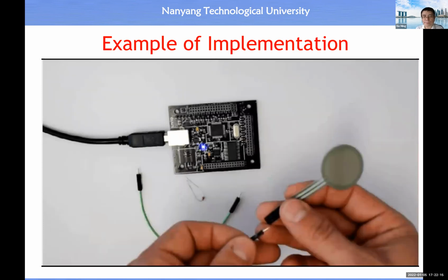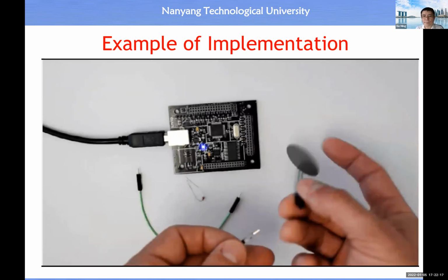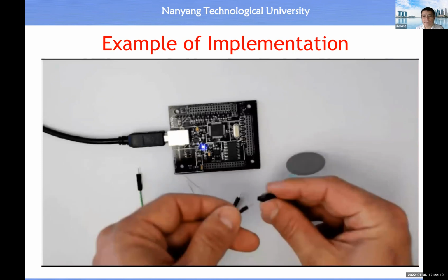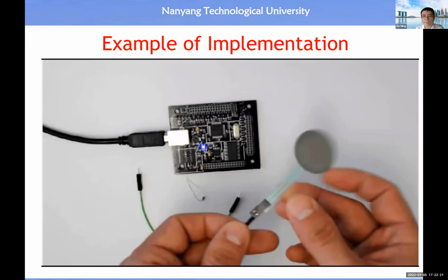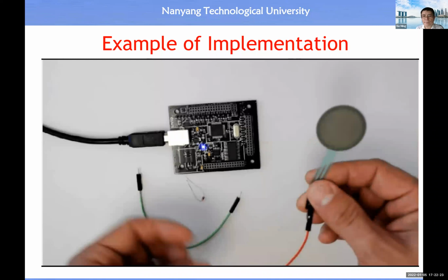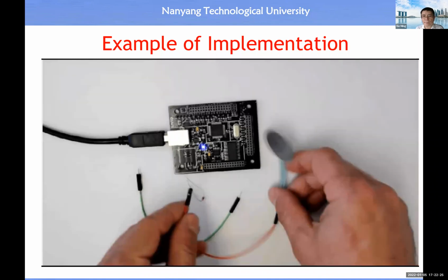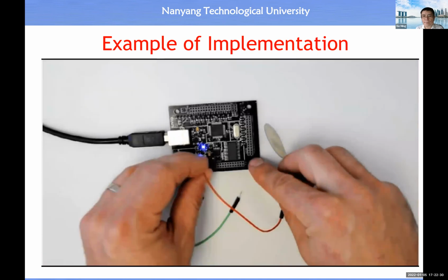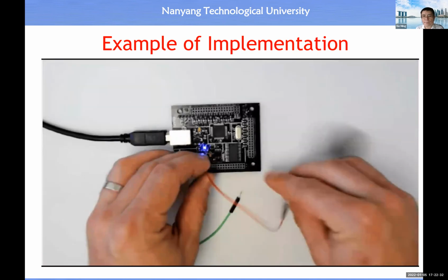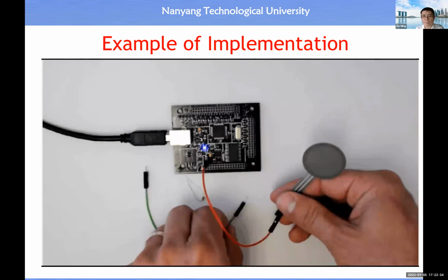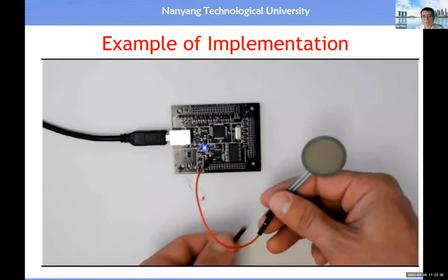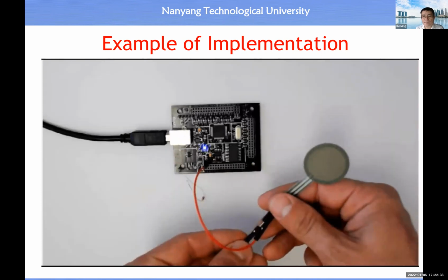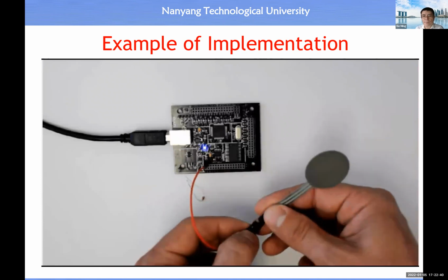And the way this FSR also has these jumper connections here, so I can easily plug it in. So I'm going to go ahead and connect one of these lines to the inside, which is my voltage. Connect the second line, and you can do this either way. It's just going to register your value differently. So there's no right or wrong way to plug these two in here. You just have to make sure you're following this.